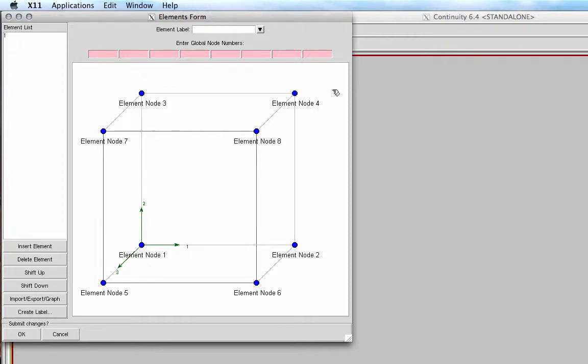By convention for meshes defined in curvilinear coordinates, we make xi1 coincide to the extent possible with the polar or theta axis, xi2 with the longitudinal z, phi, or mu axis, and xi3 with the radial r or lambda axis, while also trying to keep the xi coordinates right-handed by convention.